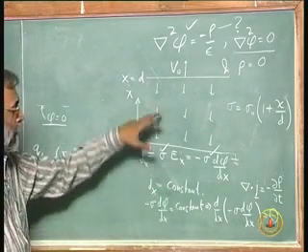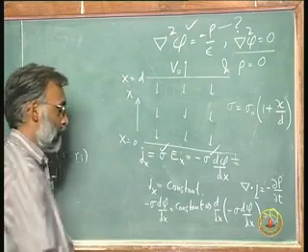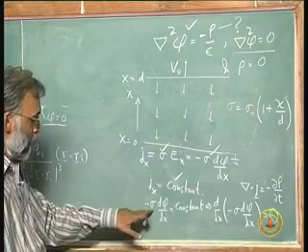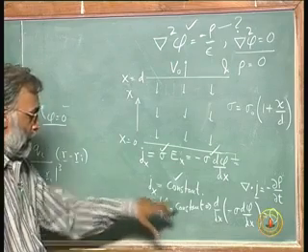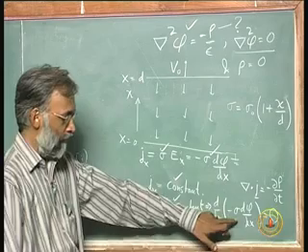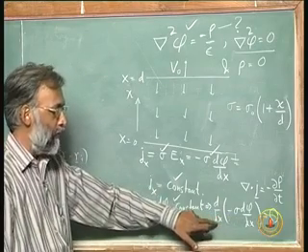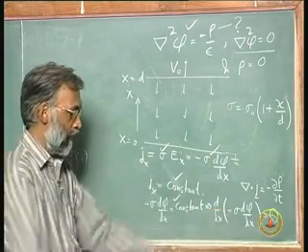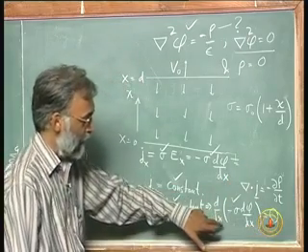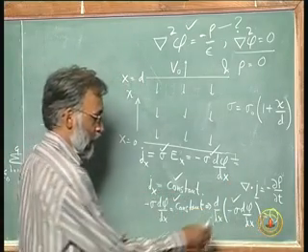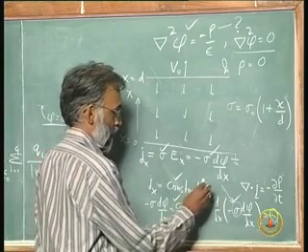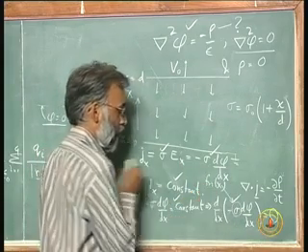J x being constant, well, that follows because of DC conditions, which means minus sigma d phi/dx is constant. That is also correct, which means space rate of change of this quantity is 0. So, up to this point the equation is correct. The problem now is sigma is not constant, it is a function of x.